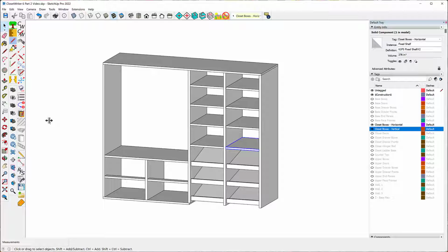If, however, you haven't done this and you don't have a cabinet or closet with a number, you'll get a message that says it didn't know what number to assign them. You'll have to assign it later. But I think the best thing to do is, at this point, to add them. Now, one of the things I didn't do, and I should have done before this, is I didn't add the backs.